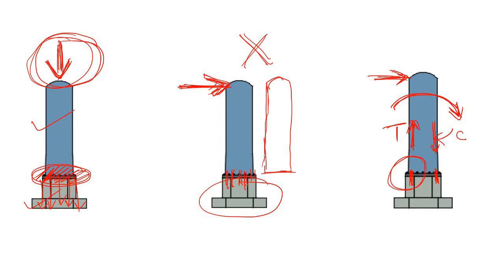You can say that this bending moment tries to tilt this vertical column like this. Here you have solved the sliding problem by fixing it with anchorage. But once you have provided the anchorage, there will be some extra uplifting or tensile force because of the end moment due to this lateral load.